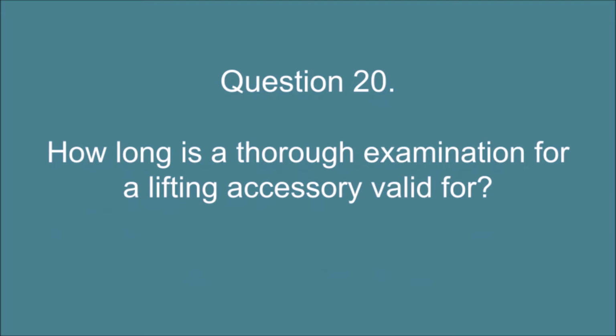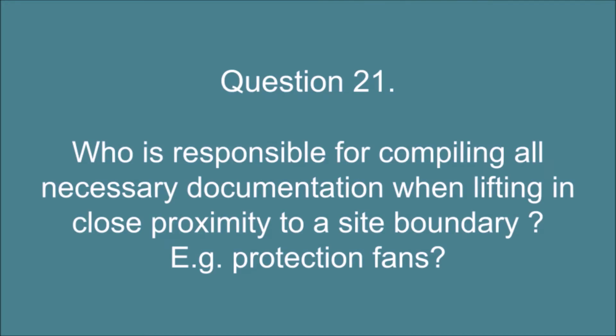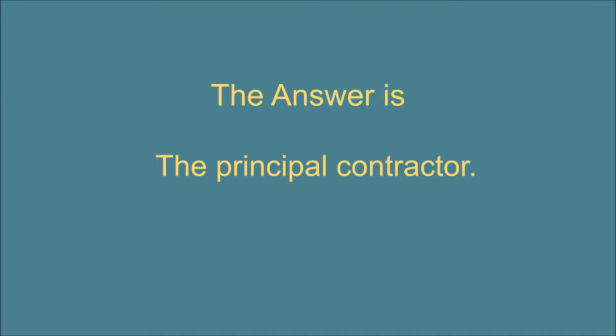Question 20. How long is a thorough examination for a lifting accessory valid for? The answer is 6 months. Question 21. Who is responsible for compiling all necessary documentation when lifting in close proximity to a site boundary? The answer is the principal contractor.